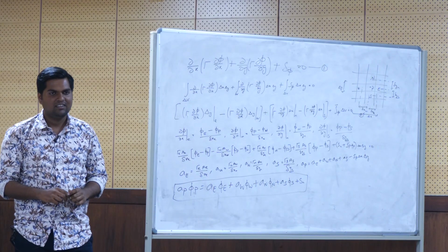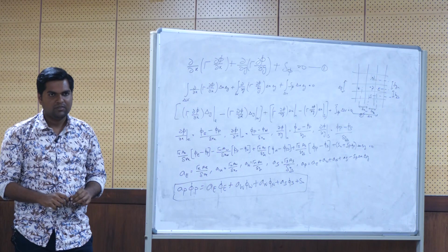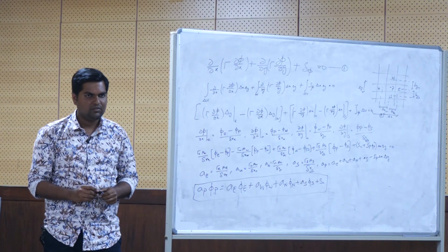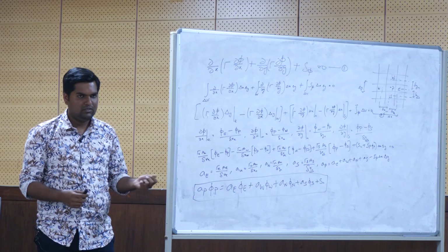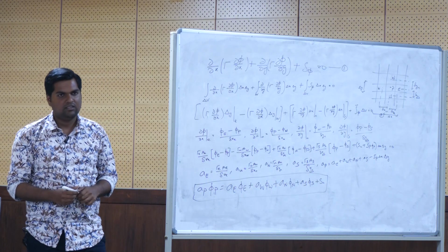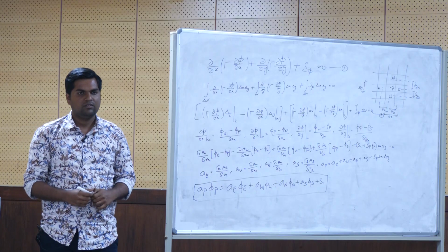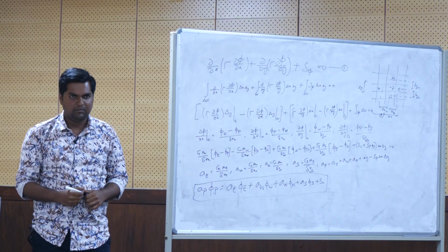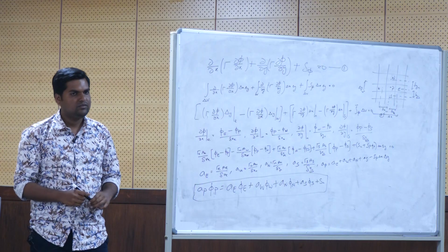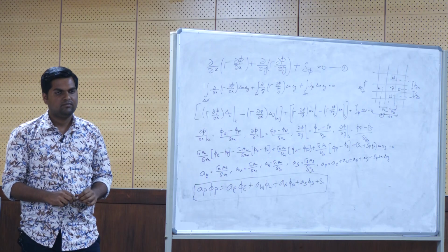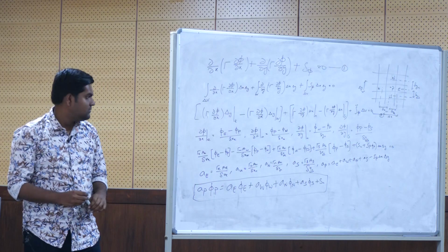Okay, so you have to work out the boundary nodes also. Yes, ma'am. Near the boundary it is half of the grid size, so del x by 2 will also come, and del y by 2 will also come, because you have dealt with the two-dimensional case. That also you have to write down separately. This is for the internal nodes.